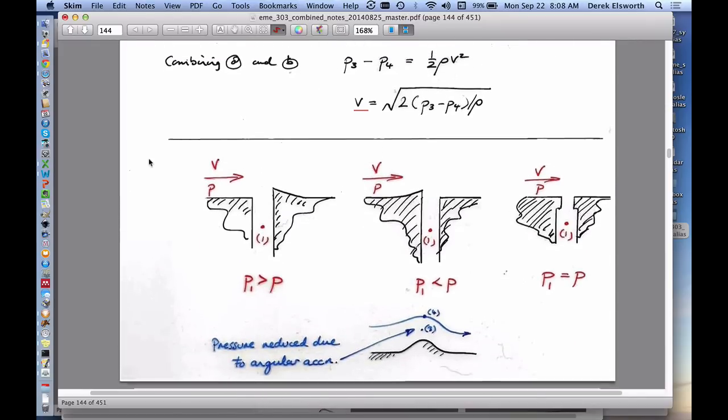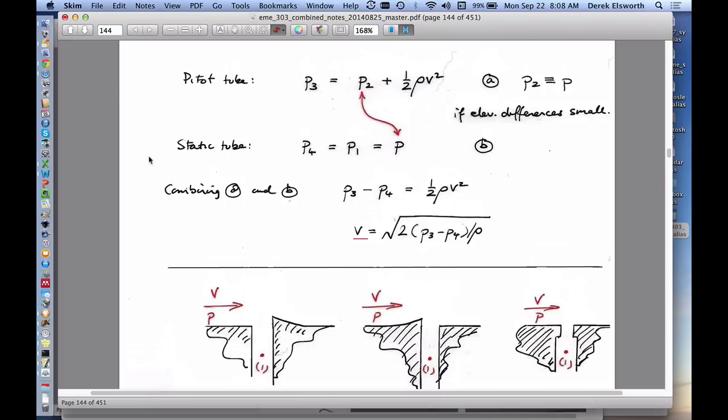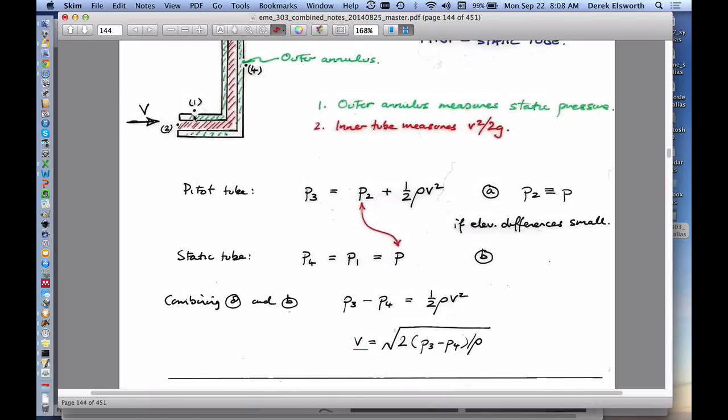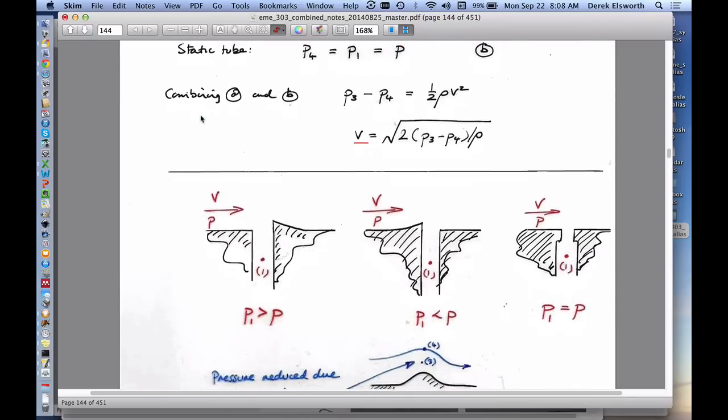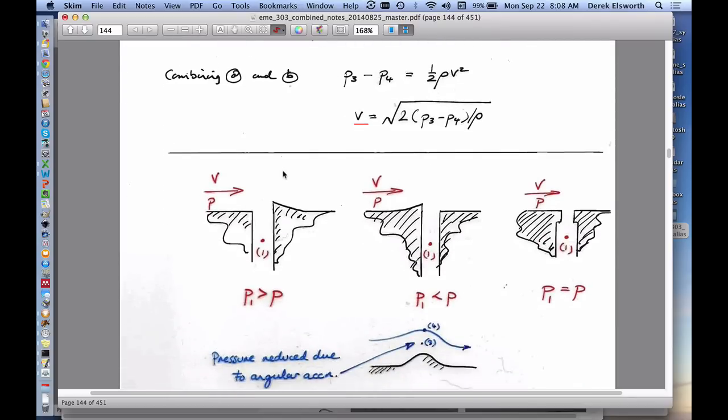You could imagine some wrinkles on that if the Pitot tube wasn't quite perfect. And so in these points here, this little hole in the side of the tube that feeds into this second green annulus, so it's a tube inside a tube, that's why the green is on both sides. If you don't have this perfectly made so it's nice and flush, you won't necessarily measure only the actual ambient air pressure around you. And so you'd like it to look exactly like this, so that the fluid going across the top doesn't get decelerated by hitting a lip or going over a lip. And in this case, you'd expect that the pressure that you measure would be the real air pressure at that point, which you're saying is also the same pressure as the pressure 100 meters in front of you, where the air velocity is whatever it is relative to the plane.